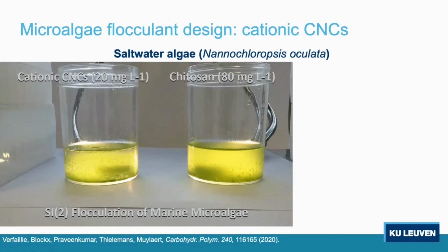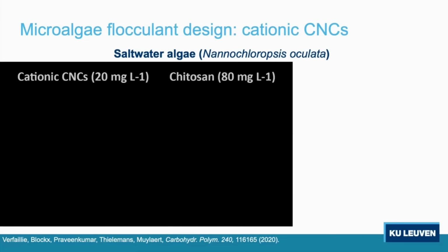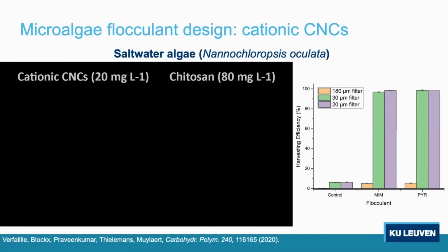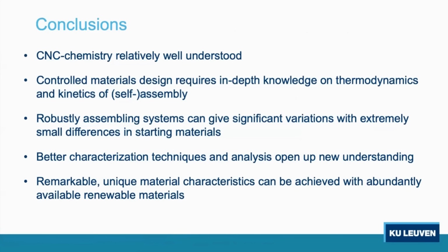Yeah, and then they stop, and you see a lot stay in suspension here, whereas there, the water actually clears very quickly, and you get nice flocculation. These flocks, you can also filter them, and you get to, with a relatively large filter at 20 to 30 microns, which doesn't give you too much of a pressure drop, and you get almost 100% recovery of your marine algae.